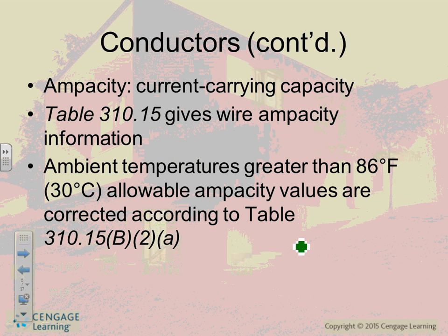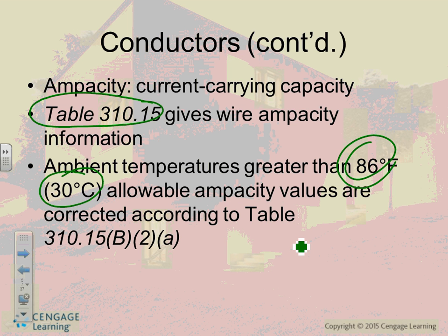Okay, ampacity, guys. Carrying capacity is in table 310.15. We talked about this table last time. These tables, guys, are for an ambient temperature of 30 degrees Celsius or 86 Fahrenheit. What happens if you go higher or lower than 86 degrees Fahrenheit, like we talked about last time? You derate. Typically, if we go lower, we don't do anything. But if you go higher, you must derate. Am I making sense? If you go lower, who cares? They will carry more current than what you're sized for.